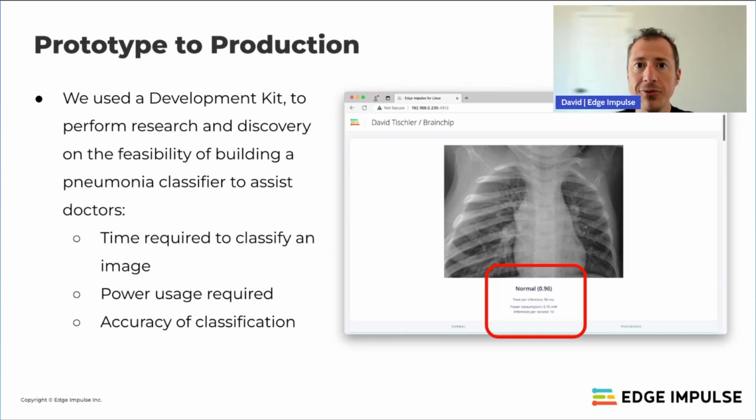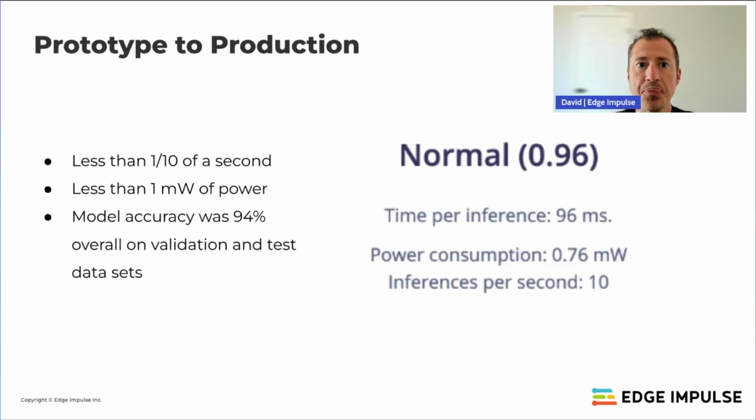The Akida Enablement Platform actually told us 2 out of these 3 items if we zoom in a bit. When using the web-based interface below the image view, if we look close, we can see that on this particular image, we came in just under 100 milliseconds to perform the classification, and we used 0.76 milliwatts to run that classifier.